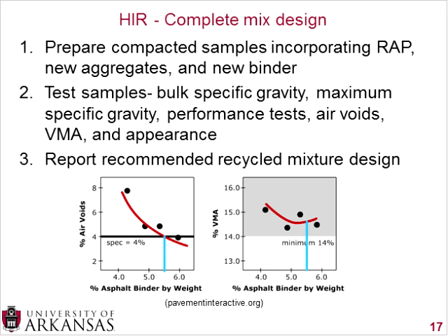One of the things you could do at this point is do a traditional hot mix design alongside of this, or even a CIR mix design if you have experience using cold in place recycling, but do a parallel mix design with something that you've already used and you have a little bit of knowledge of how it performs in the field, and then you can compare how this performs side by side in the laboratory, and that may give you an indication.